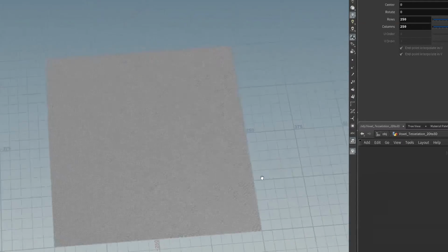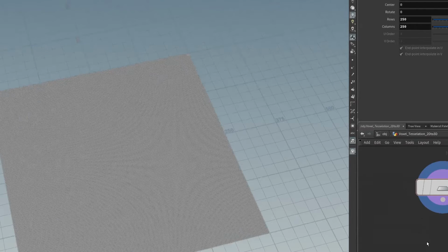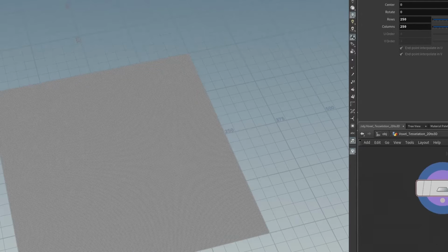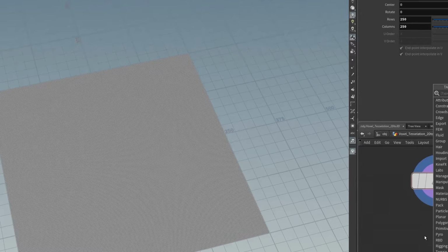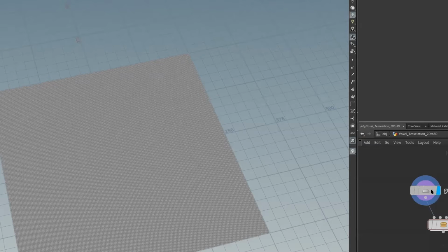Here, let's see. Now we have the grid, and under the grid, we're going to connect all the geometry nodes. It's good practice to embed the complex code in a subnetwork. So we're going to make a subnetwork connected here, so that you can always expand and connect multiple different things to this node to get different results. Once you connect this, I'm going to double click the subnet. But before we do that, I'm going to call this the voxelizer.